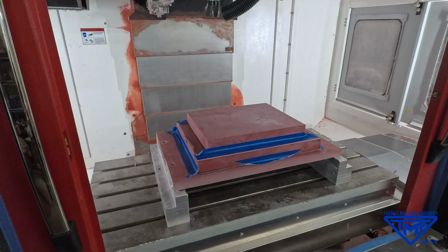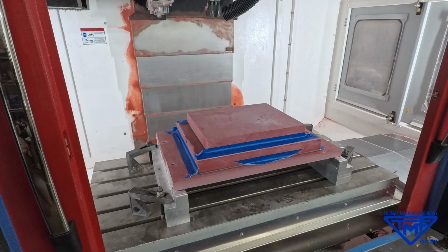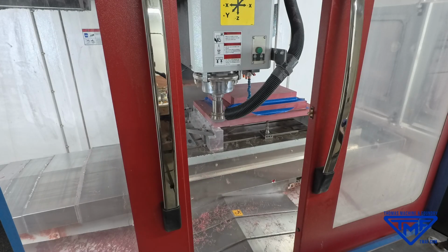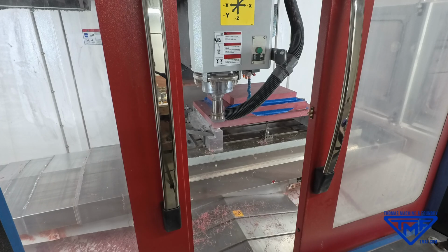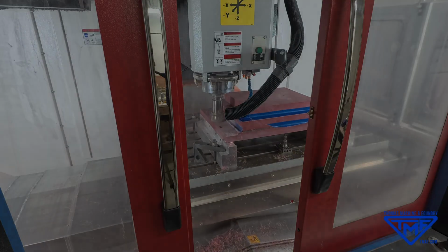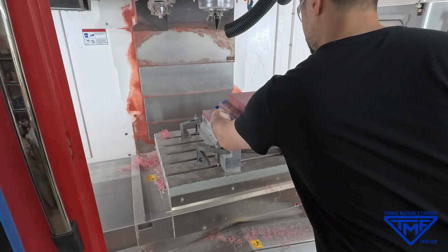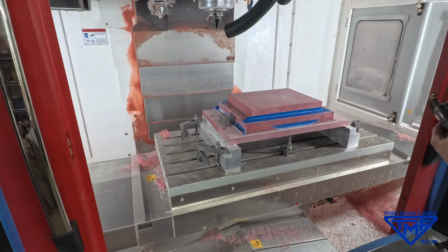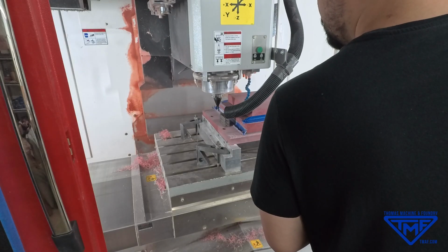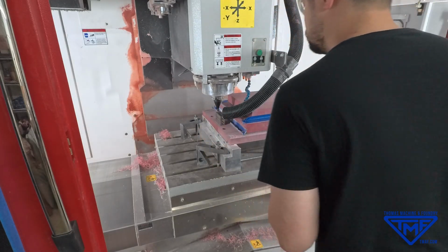With the pattern securely mounted, the parallels are reclamped onto the machine. Now the pattern is prepared for the final measurement. The top surface of the pattern is then machined flat. This creates the final Z reference plane for the pattern. From this surface, we can establish the exact height of the pattern in relation to the machine. Using a precision height block, we measure this reference surface to define the location of the cutting tools. This allows the CNC controls to understand the exact distance between the tools and the pattern surface.